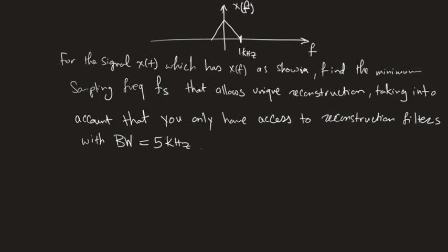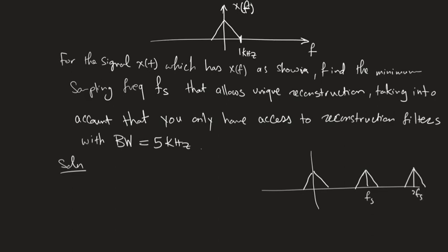So how do we look at this? Just draw the figure that we did when we were trying to derive the sampling theorem, right? So in order to solve this problem, you will just try to see, okay, here is what happens when I sample the signal, right? I end up with replicas happening at Fs and 2Fs and so on, right?